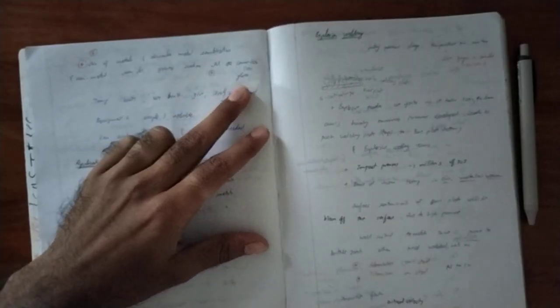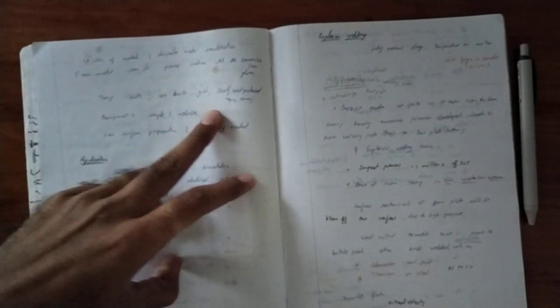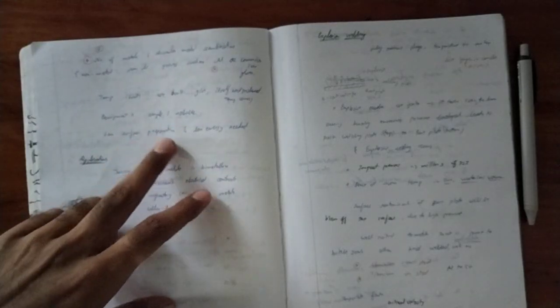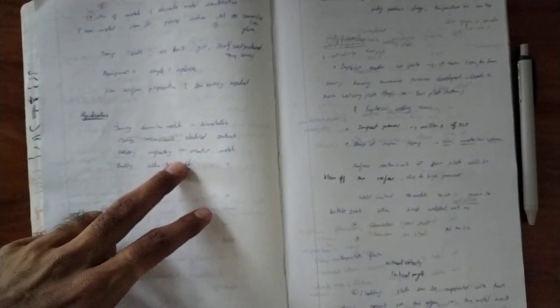Many metals and dissimilar metal combinations, and non-metals such as ceramics and glasses, can be welded. We don't give temperature; heat is produced by itself. Equipment is simple and reliable, with less surface penetration and less energy needed. Applications: joining dissimilar materials in bimetallics, making microcircuits, electrical contacts, welding refractory and reactive metals.